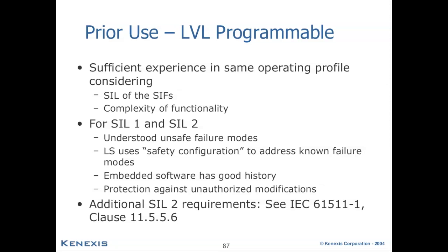You'll want to ensure that the embedded software has good history and that the device is reasonably protected against unauthorized modifications. For SIL 2, additional requirements are demanded in terms of a formal assessment. So, for the sake of this presentation, you'll want to consult IEC 61511, Part 1, Clause 11.5.5.6 for this assessment.